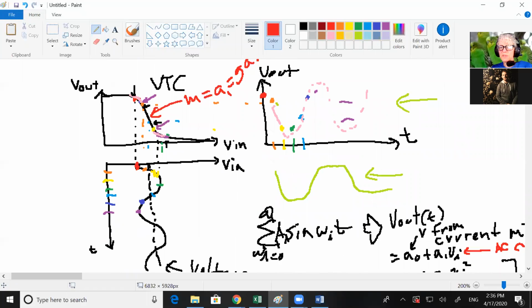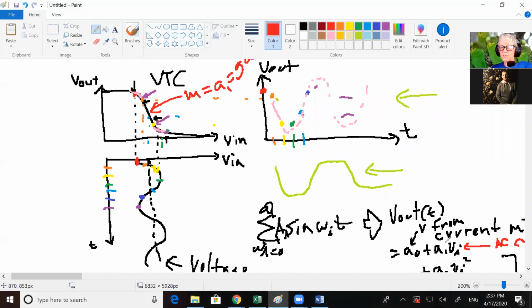So you can see from this equation, when you're describing the response of the circuit, you've got your DC offset, and then you have your gain times how much your input is moving. This is lowercase, so it's how much your input changed. Okay, up to there, good?